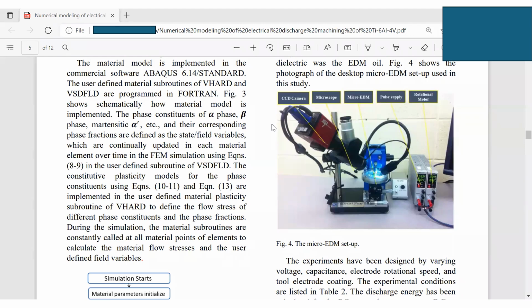After you refine your model and do the convergence, the next step is that you need to validate the model. Last time I told you to jot down what I just said. The first step is to do the convergence test to make sure your simulation results will not change if you change the mesh size.